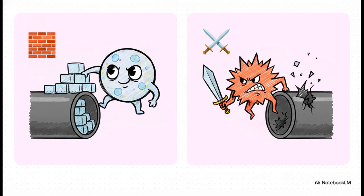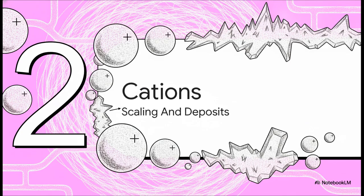On the flip side, we have anions. These are negatively charged, and they are the attackers. They create highly localized acidic conditions that literally eat away at the metal. We're talking severe pitting and cracking. Together, these 2 just absolutely tag-team your system, accelerating boiler corrosion and ruining turbine blades. Moving right along to Section 2, cations, scaling, and deposits.